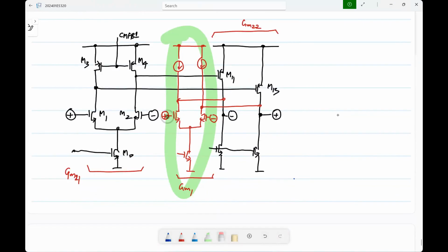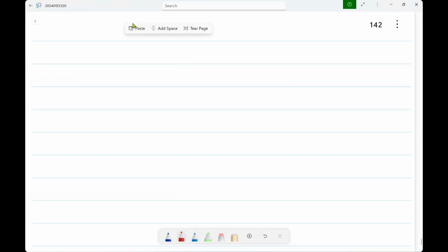So now this is connecting directly between the input and the output stage. So if you do this, then you will definitely have compromised swing limit. Okay. So this limits the output swing. Now, depending on the swing that you want, you may have to either live with the limit or you may have to do something else. And the other possibilities.